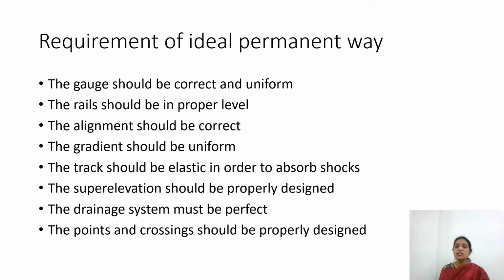Next, the track should be elastic in order to absorb shock. That means the materials we are using in the rail, ballast and sleeper should be able to take the load. As it has the elastic property, it can take shocks and vibrations without any failure.